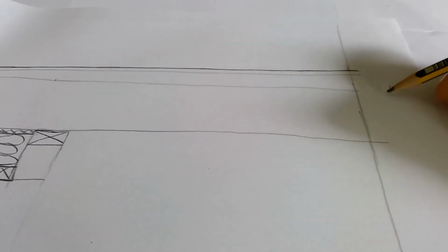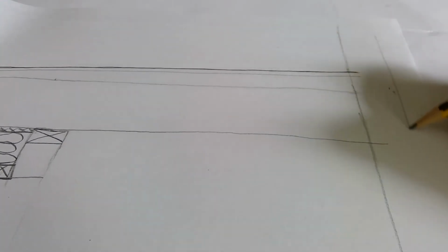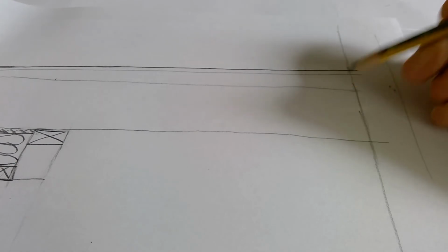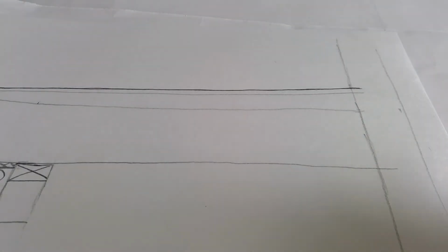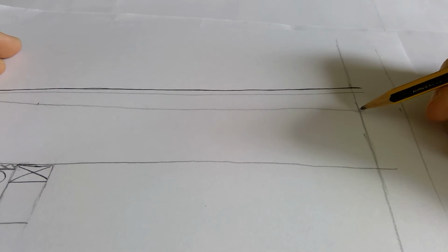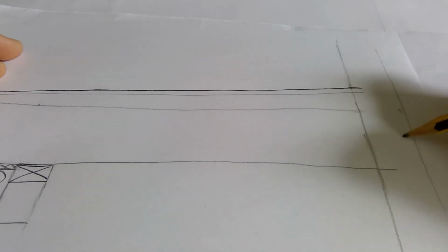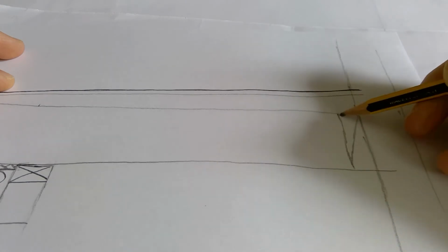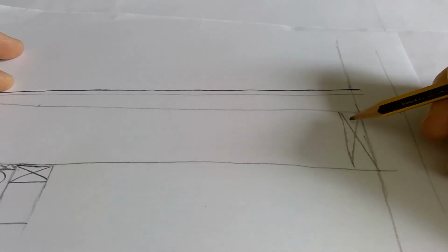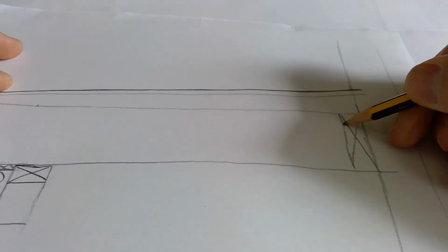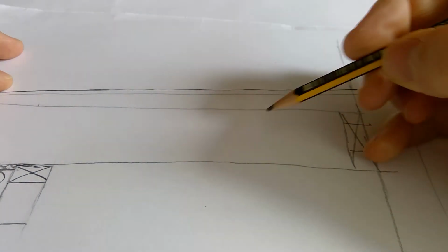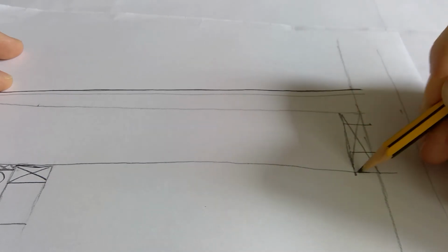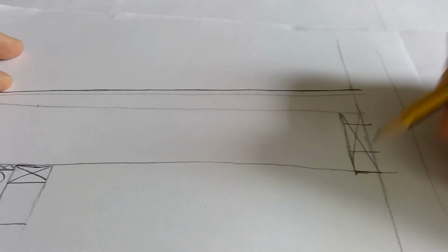Alright, draw your cavity wall. Again, you should have the full cavity wall drawn in there. I've run out of space, but I wanted to show you the abutment area here, how we're going to make that look. So to help the joist stay fixed to the wall here, a wall plate is fixed to the wall, so that piece of wood goes along that way. It's nailed into the wall, and that allows us to fix this joist into this using joist hangers, as they're called, but that just sits into place like that.